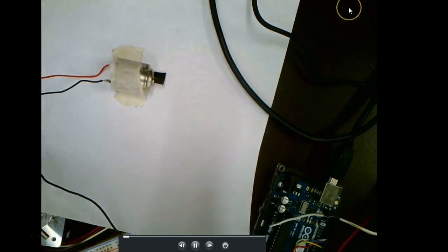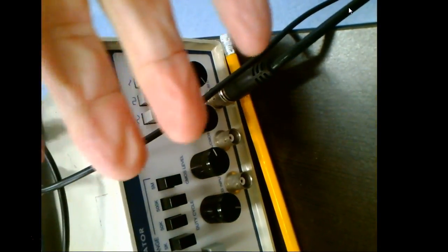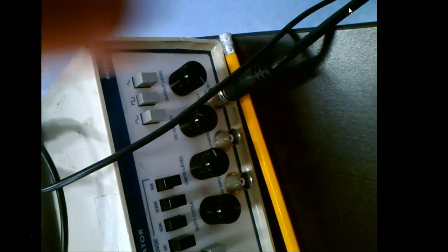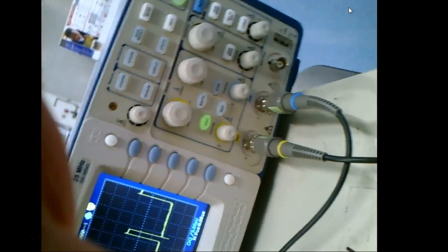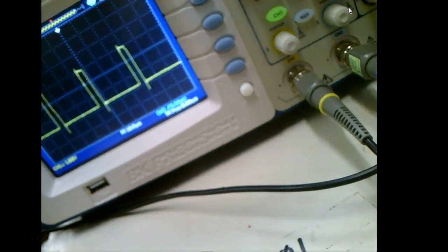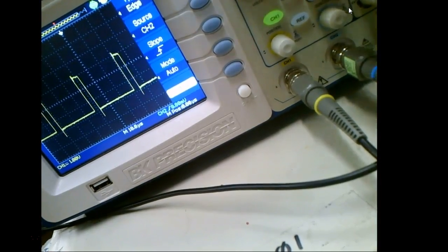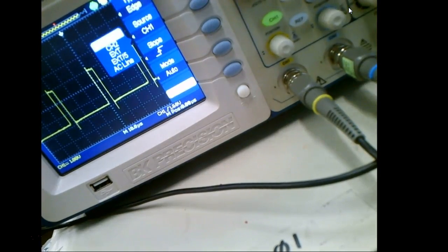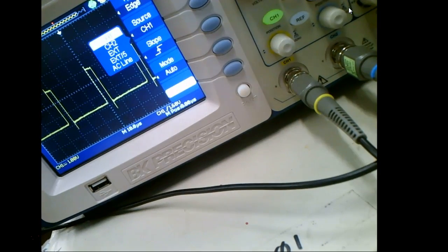So what I'm doing is I'm taking the output of my function generator, which is this electronic device down here. It gives me the ability to generate electronic signals. So we've got it on pulse, right? And then we have it set for DC. And this is the signal I'm getting, and the scope's having problems triggering. Let me check. Oh, no wonder. So let's trigger on channel 1. Okay, here we go. So that should make it work okay.